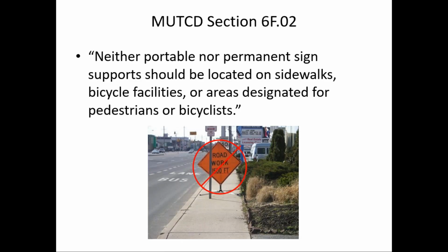This is work in the road, apparently, not on the sidewalk. And so these devices, of course, are required also by Part 6 of the MUTCD. And its placement here now creates an inaccessible sidewalk on this block that pedestrians can't use. And like I say, it's a challenge.